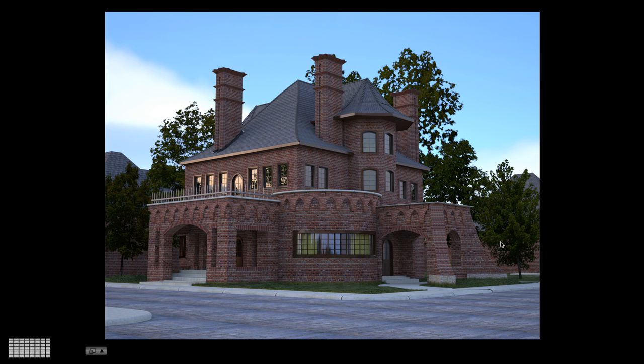I'm going to start with the HDRI version. So here is one where I haven't set up any lights at all. I've loaded in an HDRI, downloaded from the internet, and I've simply rendered the image. And you can see that while I get a very, very realistic result, I don't have some of the things that might make the image more interesting, like the direct light, adding the shadows to the scene and so forth. I also have a very even illumination all the way around. So it looks like a storm might be coming, or it's early morning. So this is nice and realistic, not what I want.